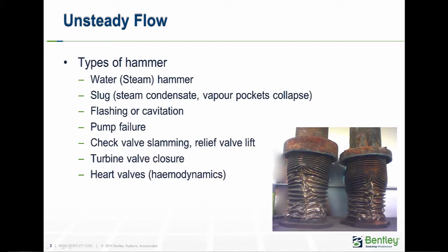Elastic forces are produced in a pipe when these flow conditions change. In general, the speed at which the change occurs dictates the severity of the elastic forces that exist, and where they occur rapidly, as in fast-acting valves, then they should be considered in the piping analysis, as they can lead to structural failure of pipes and/or supports.